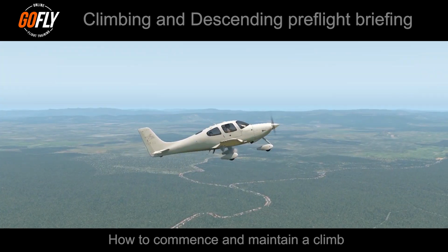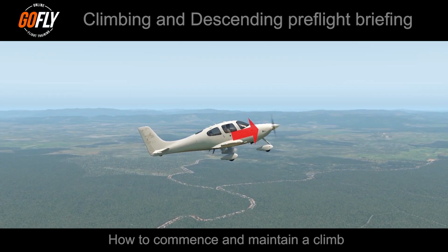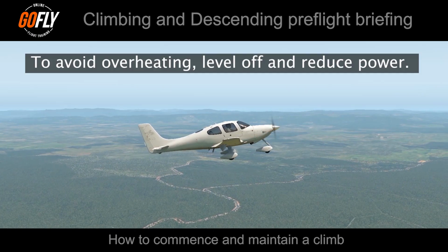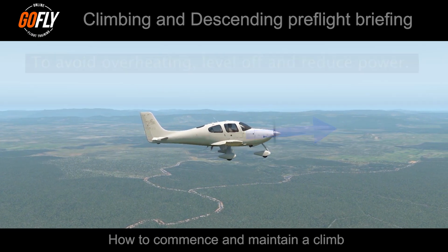In a climb, we have a power setting and less airflow going through the engine, so it is possible the engine may overheat. If the engine was overheating, the pilot would need to level off to increase airflow and then maybe reduce power until the temperature had decreased.